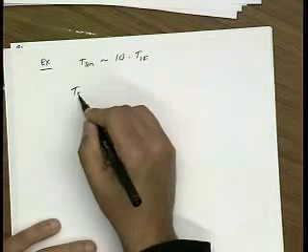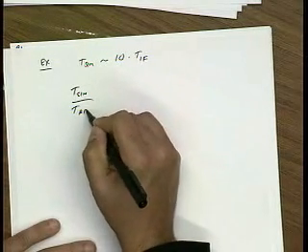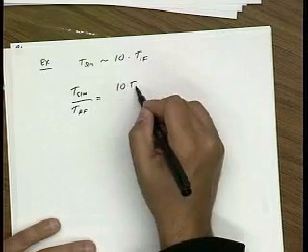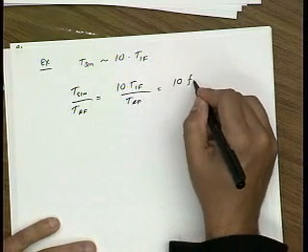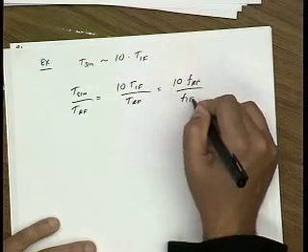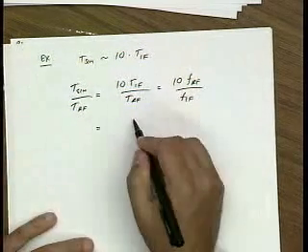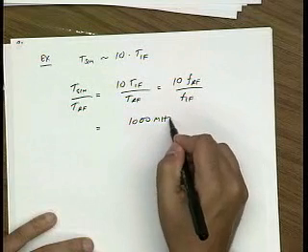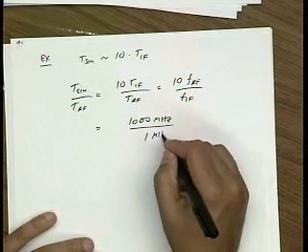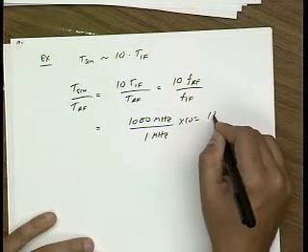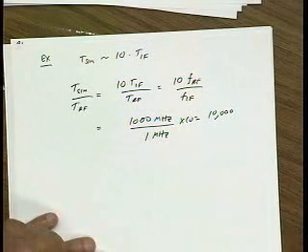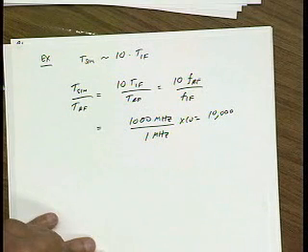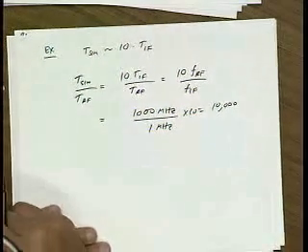And that means that if I look at the number of RF cycles within the simulation time, this is related to the frequency of the RF divided by the frequency of the IF. In this case, the RF is at 1,000 megahertz, the IF is at 1 megahertz, and that's 10,000 cycles. Okay, so that's a lot of cycles.